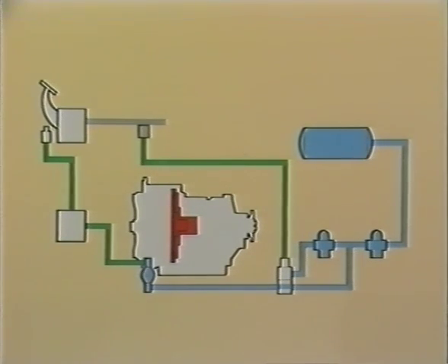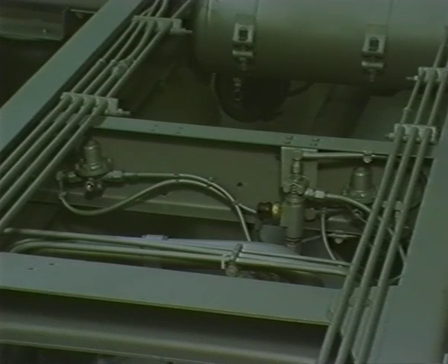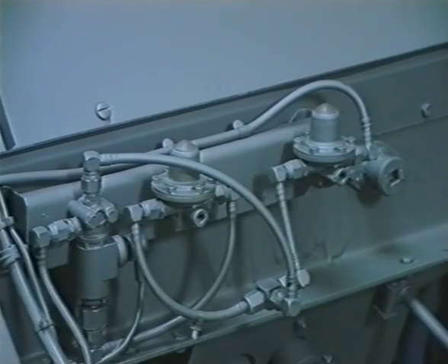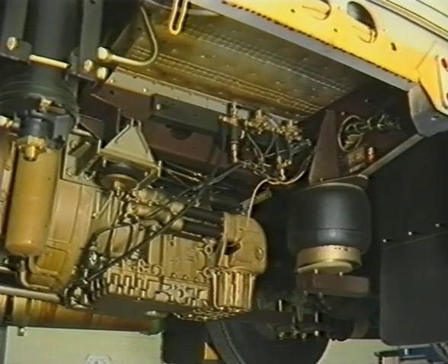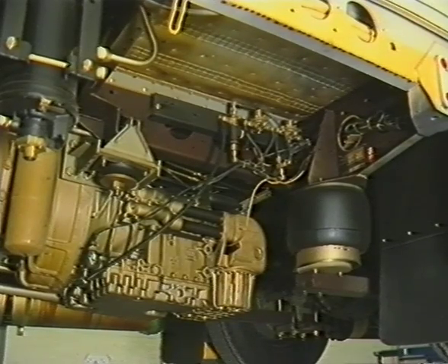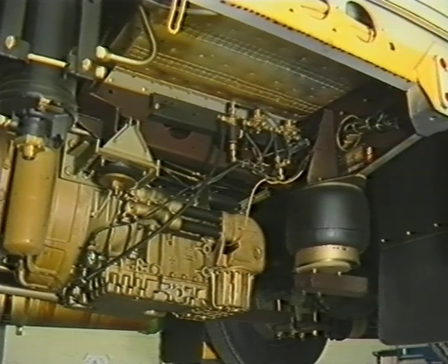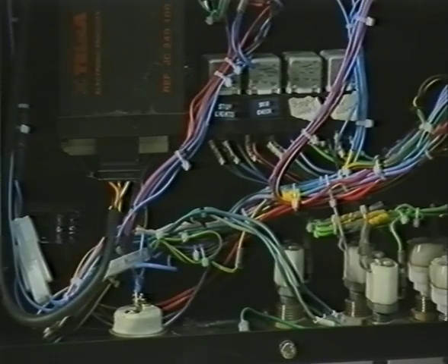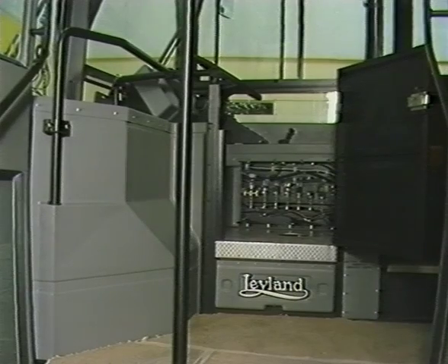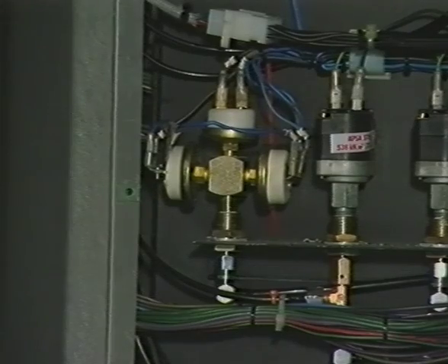The pressure limiting valves and the MV4 solenoid are located in the following positions: on this cross member on the Tiger, on the engine bulkhead on the Olympian, and on the right-hand under-frame side member on the Lynx. The second stage pressure switch is in the front junction box on the Tiger, in the driving compartment on the Lynx, and close to the foot brake valve on the Olympian.